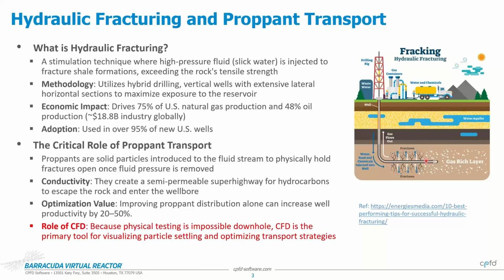And this is where a tool like CFD actually plays a role, because it's almost impossible to visualize what's happening downhole. And so using CFD models, you're solving your first principles governing equations down here. So you can then visualize where these proppants are settling down, how they're moving, the complex interaction between the liquid and the solid. And then you can think about optimization strategies.